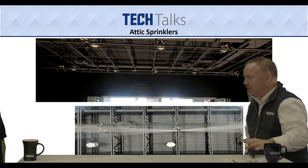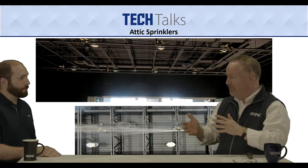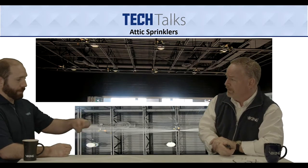6 feet. That sounds familiar, because when you go back into that video, remember the video had the fire growth, and by 11 minutes it was only 6 feet wide. Right. So we're going to be putting sprinklers every 6 feet down this, but only down the peak of the roof. Yep, if you're using just a single line.